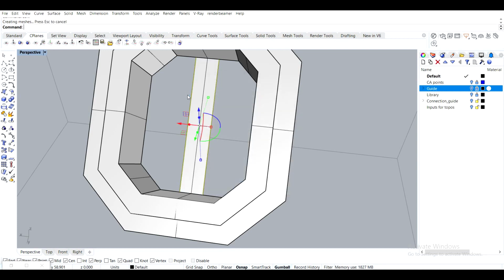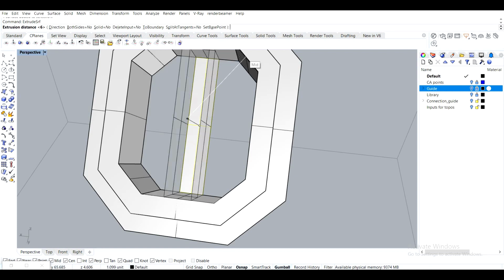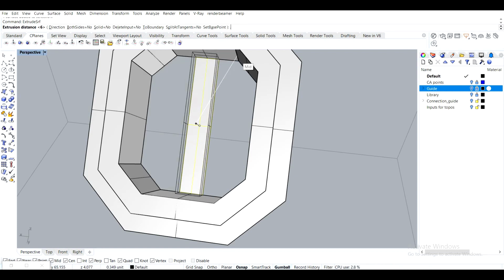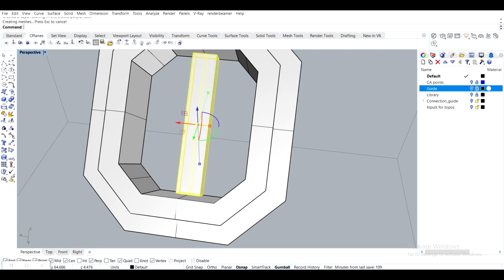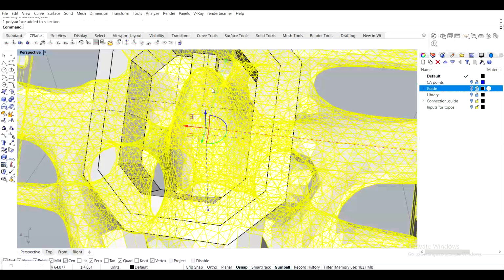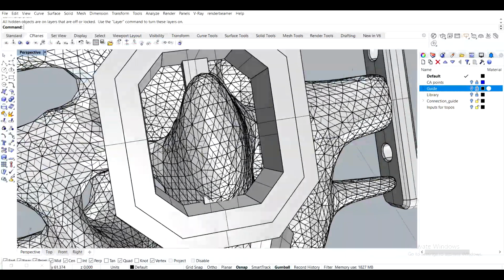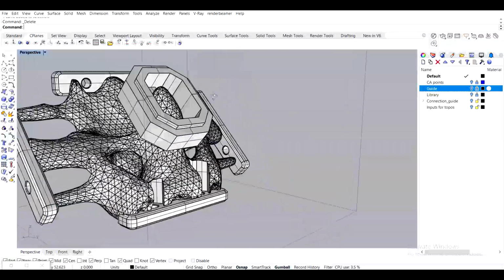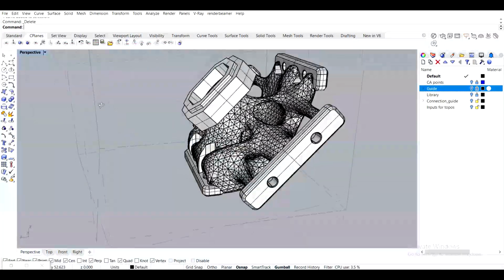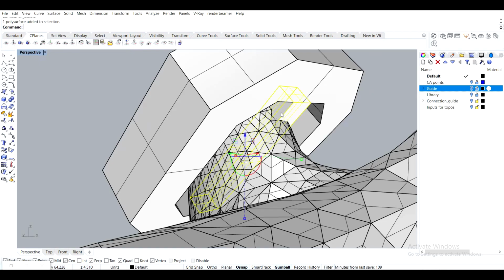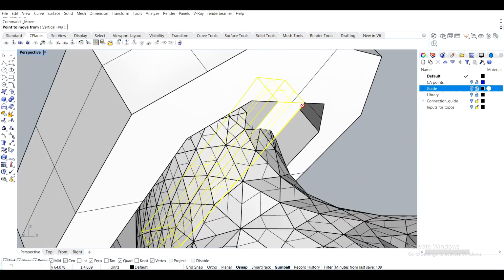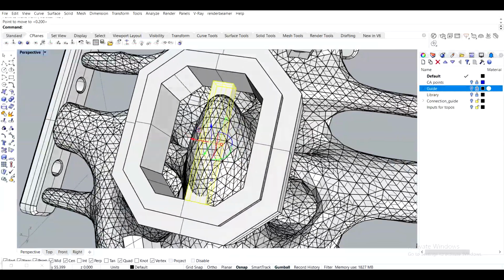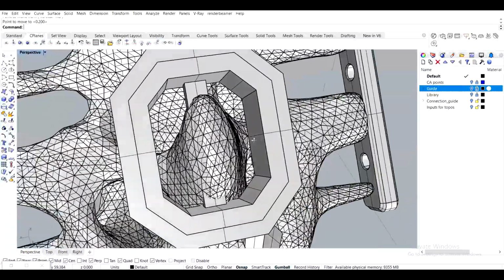Loft. Okay, delete. Extrude surface upwards until, let's say it's gonna be 3 millimeters thick. Cap it. Show selected. Show this one. Yeah, that's all I need, right? I think that's all I need. It's gonna look like that, and that seems okay. Maybe it can be slightly moved inwards. Doesn't mess up. That's good.